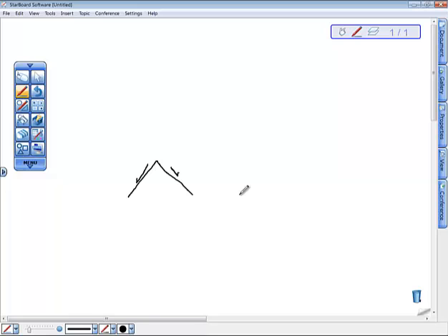When you have a flat roof, or a relatively flat roof, usually there's a parapet wall on the end. I'm drawing a little section here. So you can have a single slope all the way down to here and then have some sort of scupper through the wall that lets the water flow out.